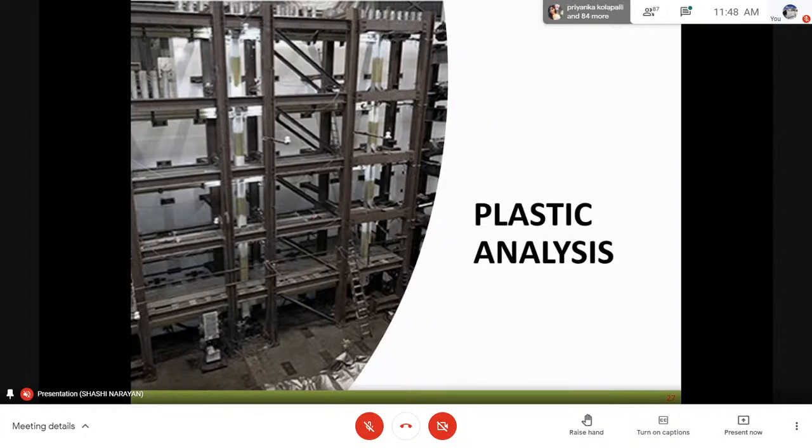What is MSK intensity? MSK intensity, if you look into the code, is based on both the effect of the earthquake as well as the energy content in the earthquake. What the effect of the earthquake is will define your intensity. If we have structural damages, then that goes into higher intensity. The non-structural damages go into lower intensity.